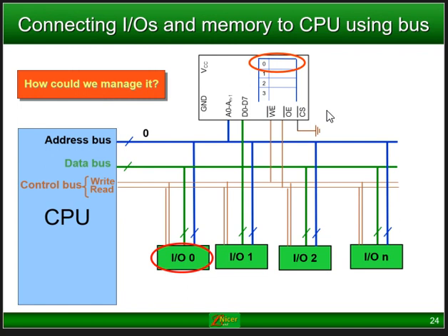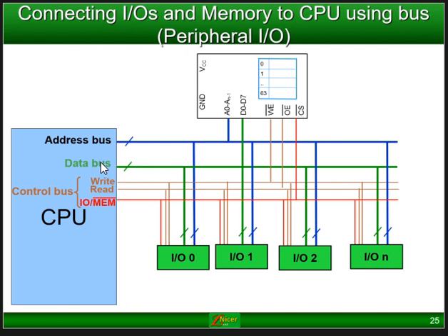As you can see here, with this device actually active here, if this address says 0, it's actually referring to that location, that address there, but it's also referring to the IO 0 here, which is in conflict. You can't have this thing addressing two separate entities. And this is why, what you could do in this specific case, there's an IO/mem